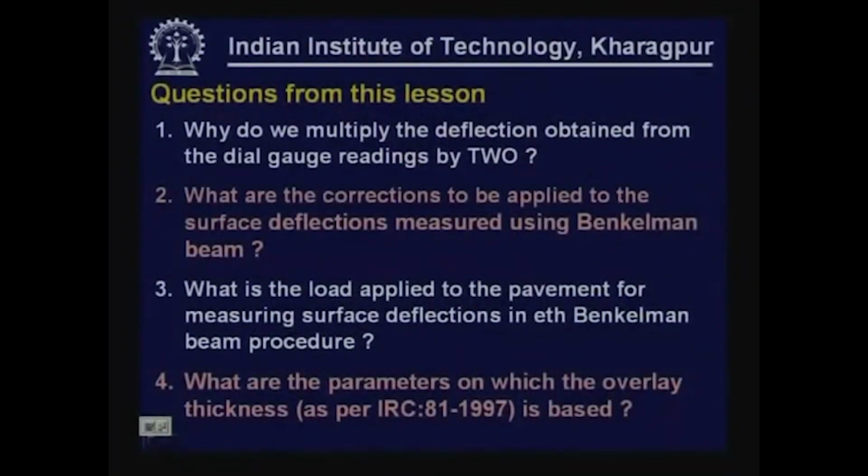What is the load applied to the pavement for measuring surface deflections in the Benkelman beam procedure? The load applied is through a truck. The rear axle has to carry 8170 kg equally distributed on both the dual wheel sets. The tire pressure has to be 0.56 MPa.